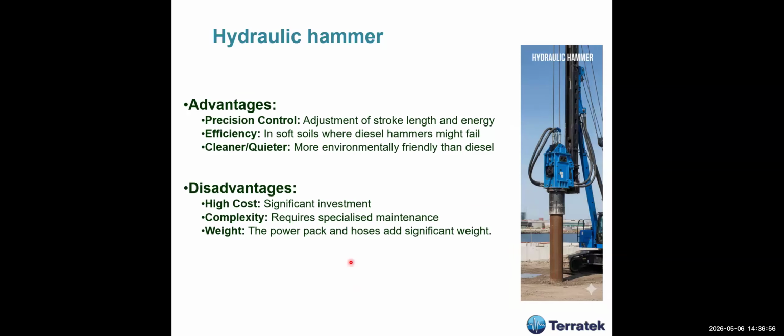The hydraulic hammer, it's excellent, but we have to adjust. You can adjust the stroke length and energy. In soft soils where a diesel hammer might fail, you can use this hydraulic hammer. It's cleaner and quieter, much more environment friendly than the diesel one.